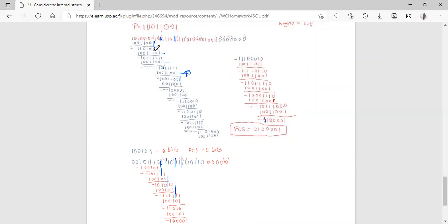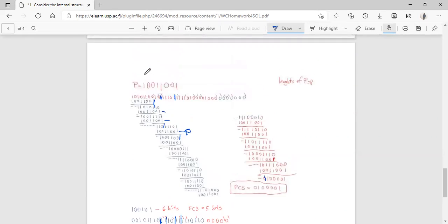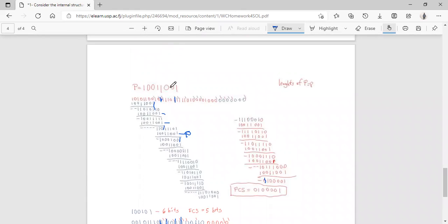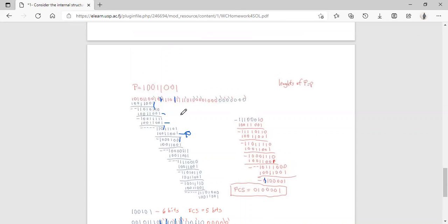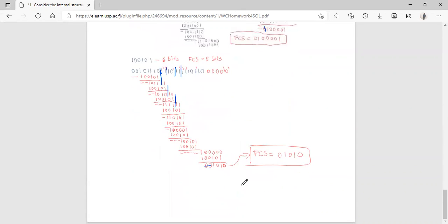And then you stop, you check how many bits you have, you compare it with the polynomial that you are performing the operation with, okay? If it's less, you carry the required number of bits from the data over here, right? Then again you write the polynomial starting from the first 1, and then you perform your XOR operation, right? XOR operation represents the modulo 2 arithmetic, right? So with that, we'll come to a conclusion, right?